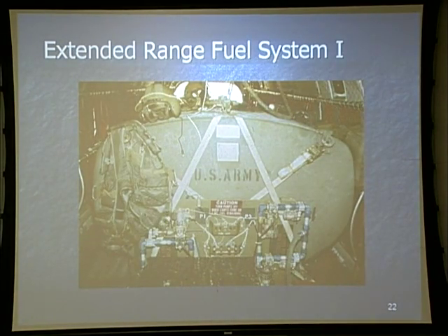That was the old IRFS 1. This is a cool picture. I'm glad they put this in there. That's what we used to fly with. A makeshift pump board. And these are just the 600-gallon pods that used to go in the back of 5-tons and deuce and a halfs, 2.5-ton trucks. They just modified them, put them into here. That's all they did. Now, they had a fuel capacity of 580 gallons based on the fact that once we put it in the aircraft, because of where the nozzle fuel point was, it would only allow us to fill it up to 580 gallons.